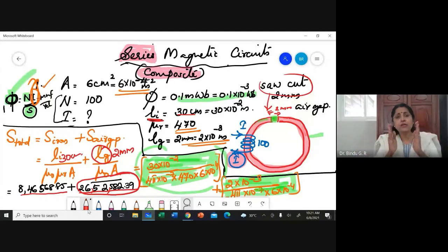It is bolted together. So in all these cases, they make sure that there is absolutely no air gap between these bolts and all these laminations, because we want more and more flux to easily pass through that core. We would have preferred a solid core, but because of the presence of some eddy current losses, we are compelled to have a laminated core.